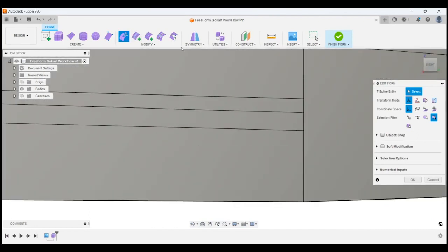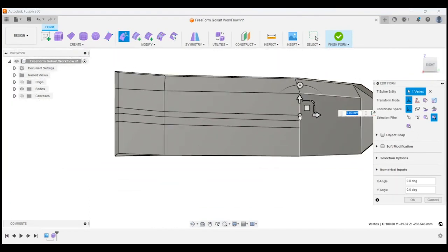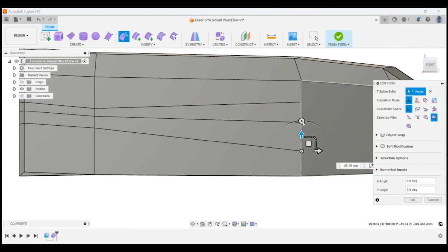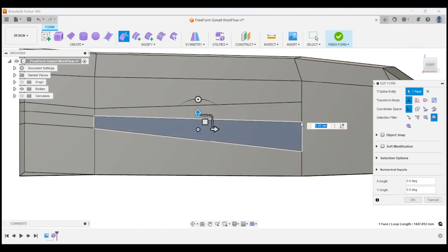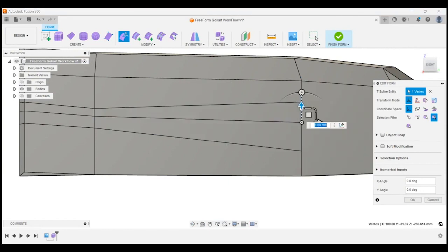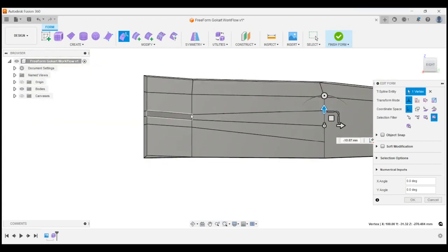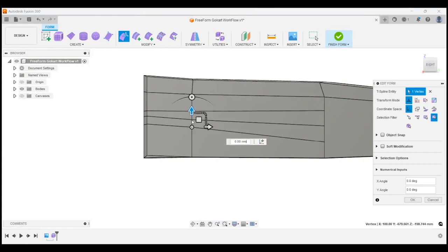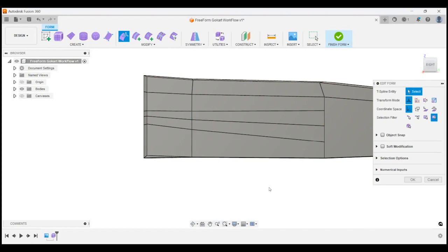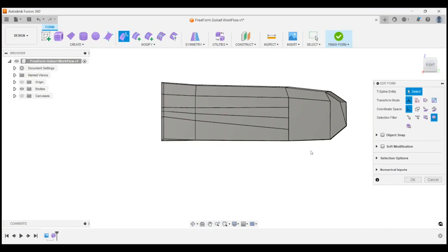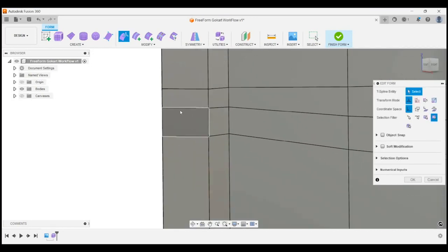Also, good practice is, I'm ending my T-points here, but they're all spaced quite tight together, so it's not a bad idea to space these out. And that just means that if they do result in any kinks, which they sometimes can do, on a smooth face even, that they're not as sharp, and you're less likely to get problems in geometry by spacing them out a small bit, so it's no harm to do that. So just notice all my lines nice, consistent, relatively parallel, and even the ones that aren't, we're going to come back to them and clean them up.